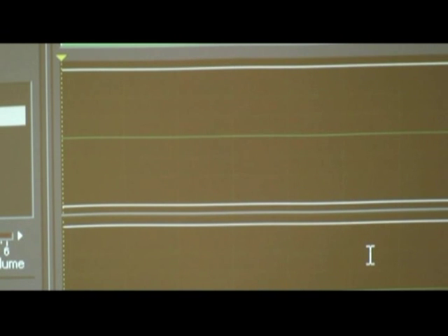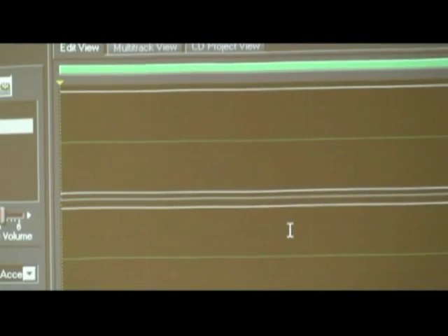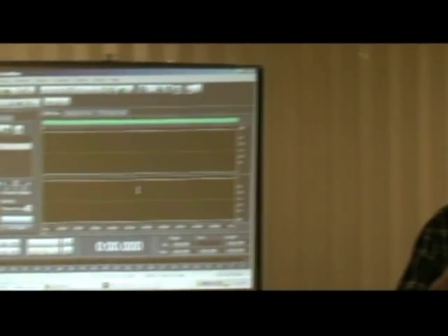Yes. If you remember on audio tape, broadcast quality was 30 inches per second, 15 inches per second. Home use was usually 3 3/4, 7 1/2. Then it became 1 7/8. Audio cassettes are 1 7/8. As you're traveling at a slower speed, you're pushing a lot of information into a short amount of space. And that's linear. Digital is kind of like that, except you're sampling information. You're either getting a lot of information to get all the finite little intricacies, or you're just grabbing what you need.